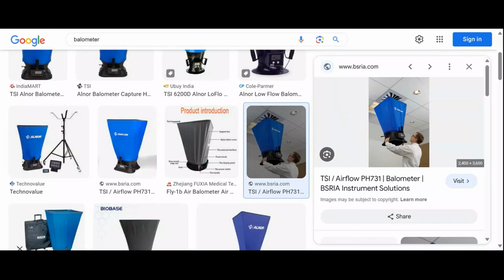For 20 TR, we can directly opt for a package or ductable split unit. Ductable split is available up to 22 TR, right? Yes. Then why do I need to go with all that much hectic work? When I go with the chiller system, the maintenance also increases, obviously. So that is the thing.